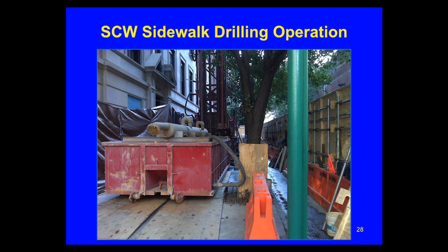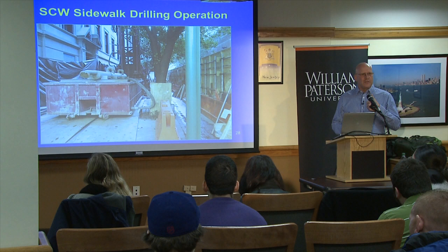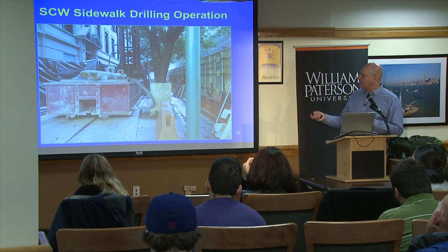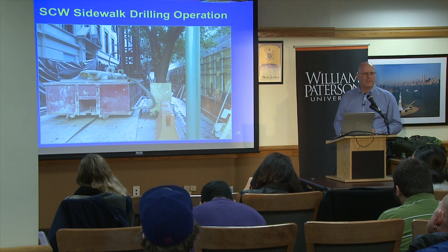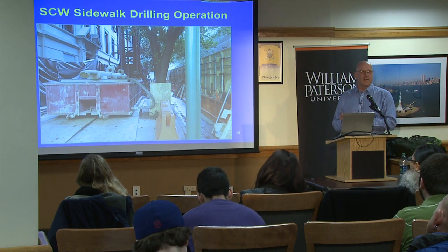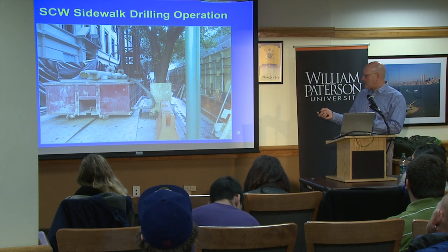That's what the drilling equipment does. It's pneumatic, and it's basically like a hammer. So air is being delivered to work a tool that has diamond bits at the end that's hammering the ground, and then the air, through enormous delivery of air, is bringing these cuttings up. And it's going into here, which is almost like a muffler, if you will. It's basically reducing the energy that the cuttings are being lifted with, and they drop out into this conventional roll-off.